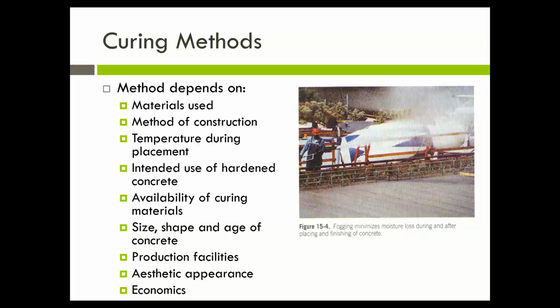And then for other aspects of where are we? Can we handle large water runoffs on our site? What about putting curing compound into the air? Is there any problems we would have locally if we had solid materials drifting through the air? And then, of course, like anything else, there's economics. The cheapest cure is to do nothing. Of course, that may give you all kinds of problems in the future. The best cure is to pond with water, but that may also be economically unfeasible.